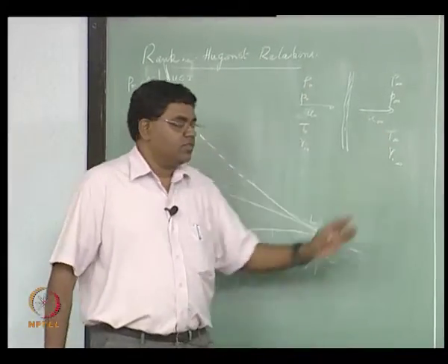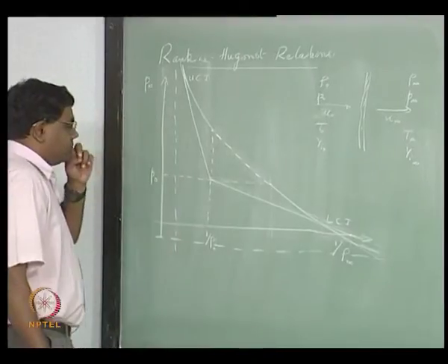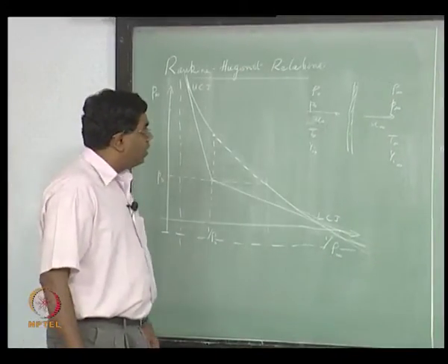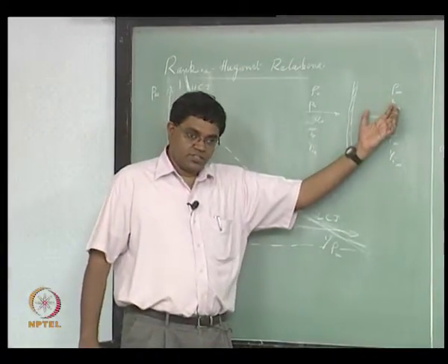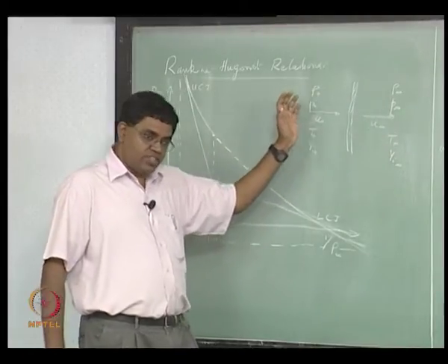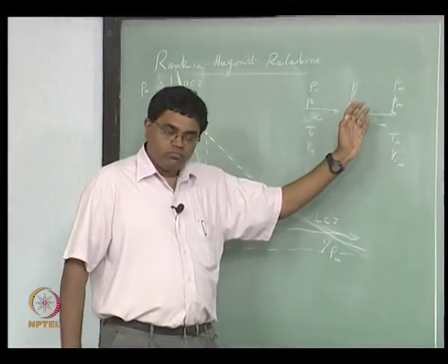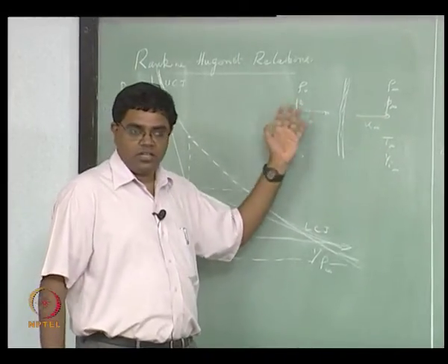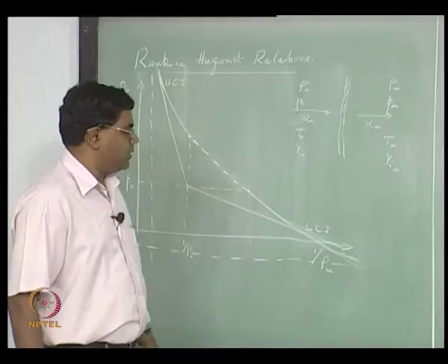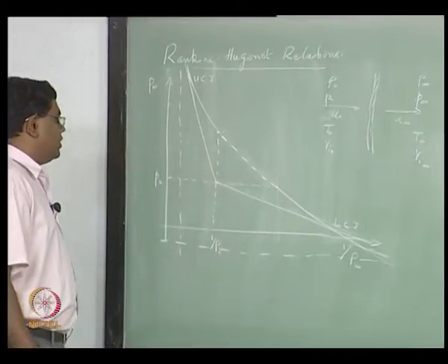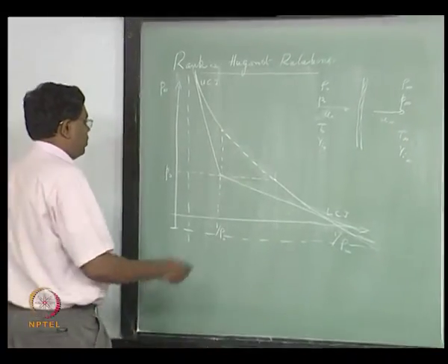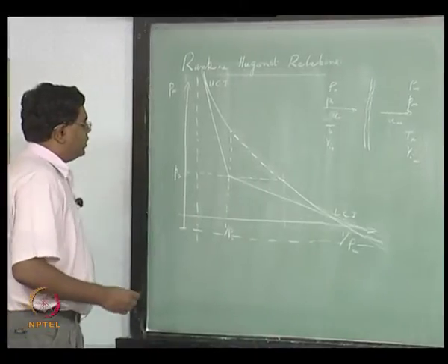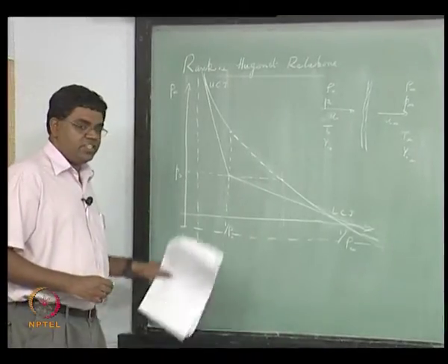Okay, so the answer there is they could decelerate all the way down to subsonic conditions, or they could get decelerated to supersonic conditions that are still slower than the incoming supersonic speed. This is typically what you're expecting when you're now looking for a detonation wave that is not a CJ detonation.